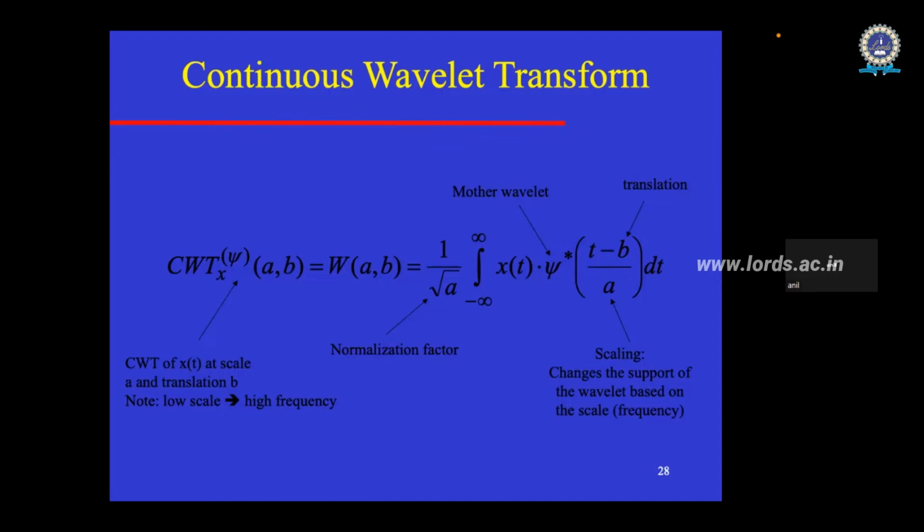For example, if I go for any non-stationary signal, the simple Fourier transform won't work. Anyway, luckily for speech kind of signals, the short-term Fourier transform works. Otherwise, the Fourier transform has very limited practical applications because practical signals are non-stationary. Apart from that, I already discussed this issue of the Fourier transform in the beginning itself.